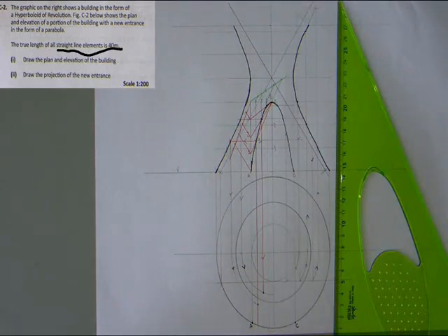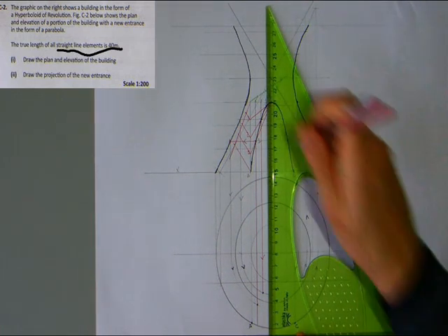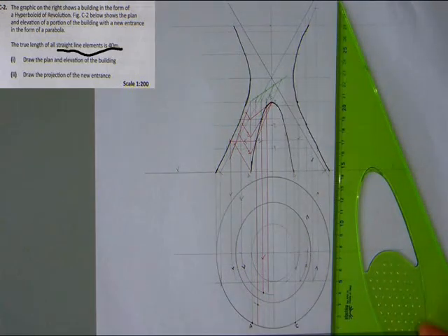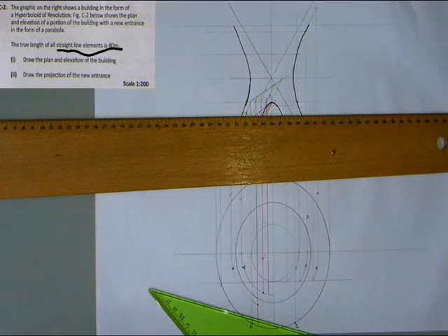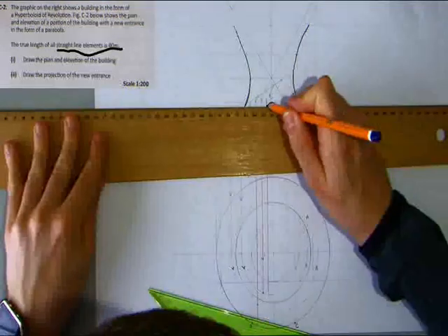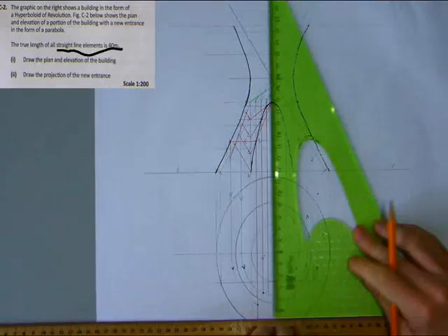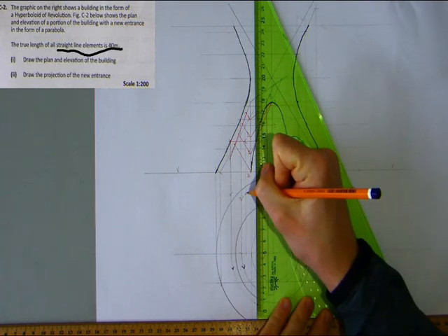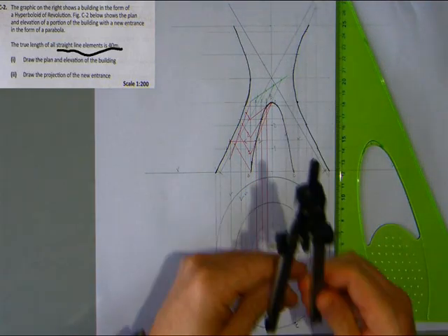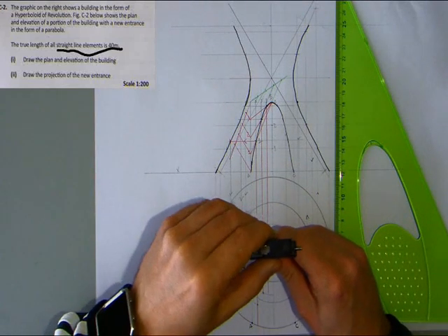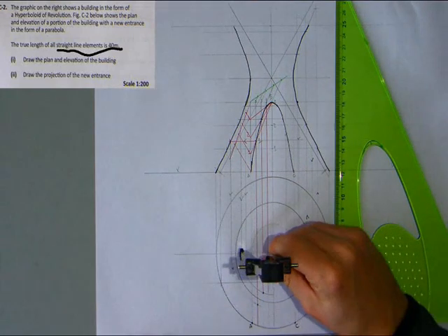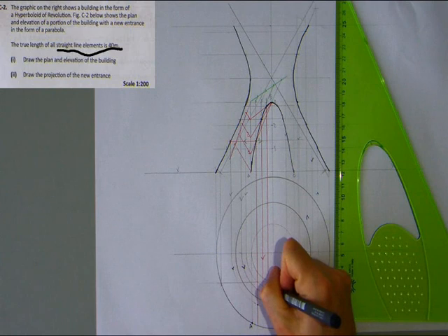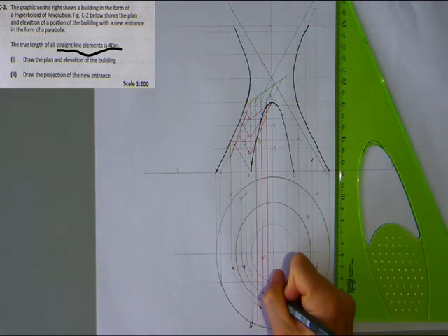Okay, we're going to repeat that process one last time. Again, here is the location of that entrance. Bring it straight down using our red pen. Let's bring it out to the extreme generator. And here, where is that location? In plan view, it's down here. What you do in one view, you must do in the other. And so, from the central axis, we rotate that round to hit our corresponding red line. And we now have point 3. So, 1, 2, 3, A and C.